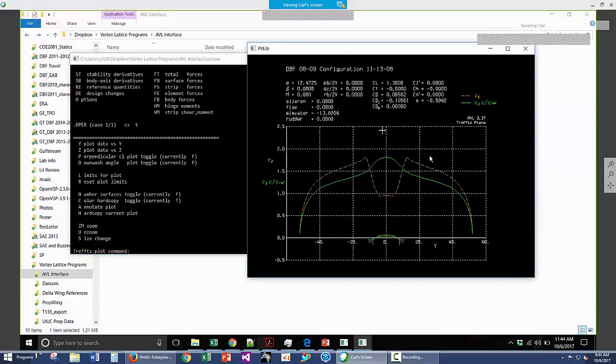And we have the results here. And maybe this has some level of stall, and maybe we ought to reduce that slightly. Looks like our actual trim CL max is somewhere more like 1.3 instead of 1.7.